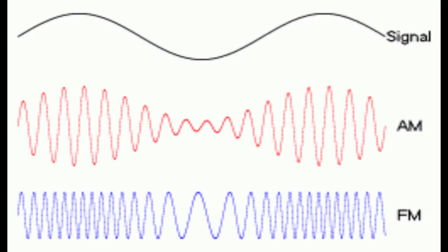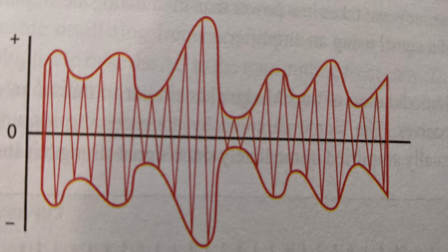Amplitude modulation, or AM. A radio wave can be altered to carry useful information by modulating the amplitude of the wave. However, AM has limited fidelity. Atmospheric noise or static alter the amplitude of the carrier wave, making it difficult to separate the intended amplitude modulation caused by the information signal from that which is caused by static. It is used in VHF communication radios.